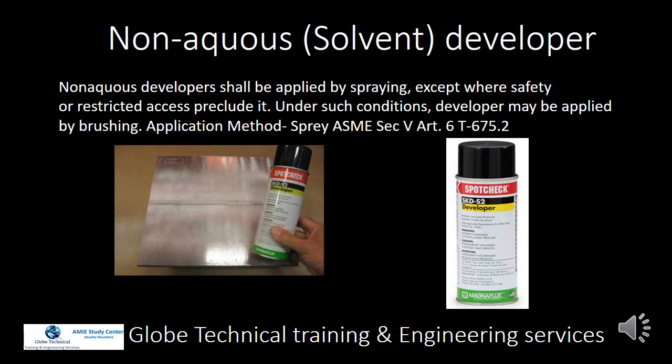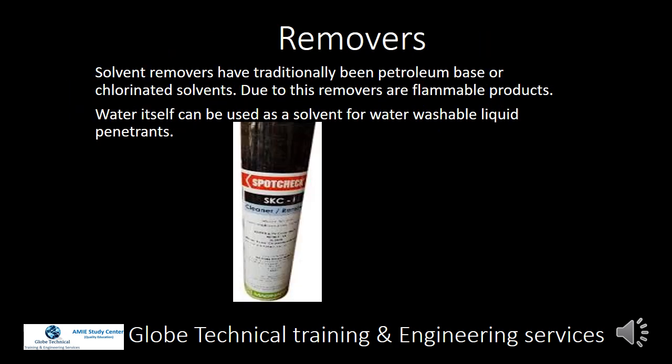T675.2. Removers. Solvent removers have traditionally been petroleum base or chlorinated solvents. Due to this, removers are flammable products. Water itself can be used as a solvent, for water-washable liquid penetrants.